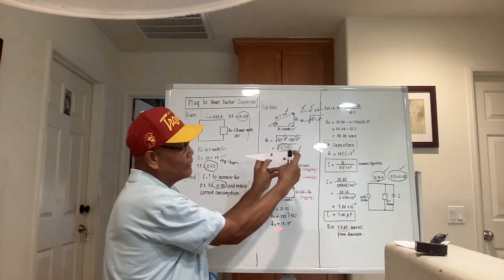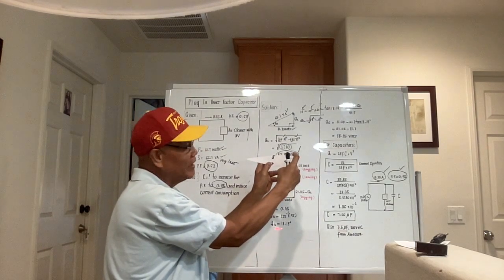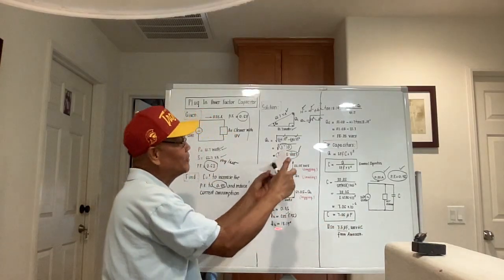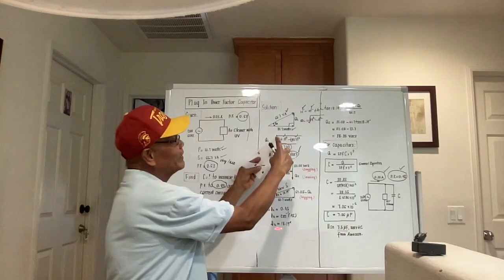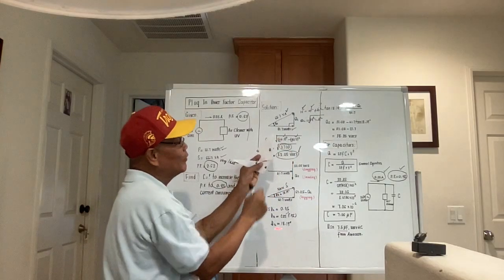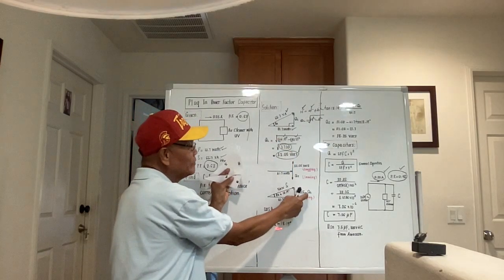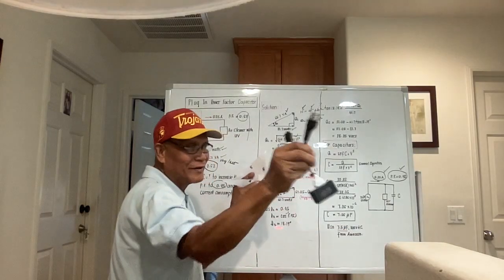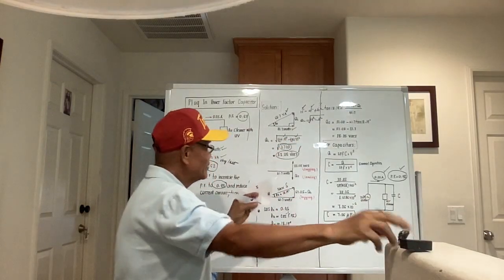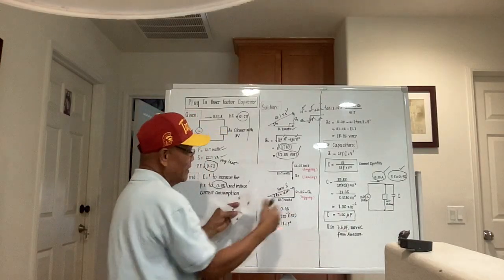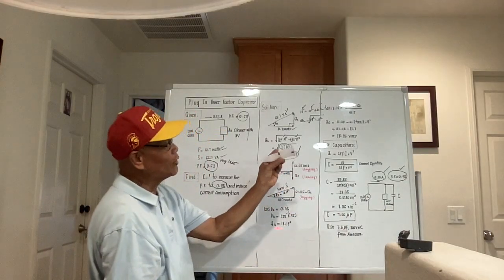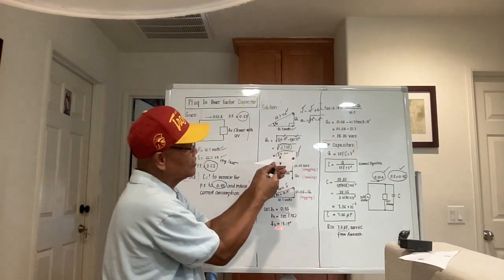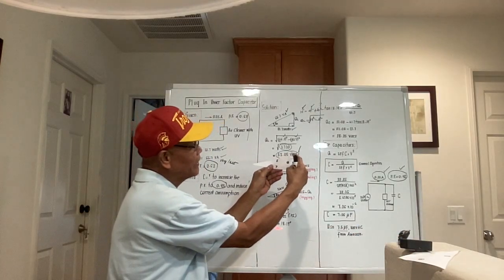The reactive component which remains is lesser now, because originally the reactive component of the motor is actually very big. But it became smaller because it was counteracted by this capacitor here, Q sub C, by the addition of this one. Right? So this becomes smaller and the resulting power triangle will be smaller.